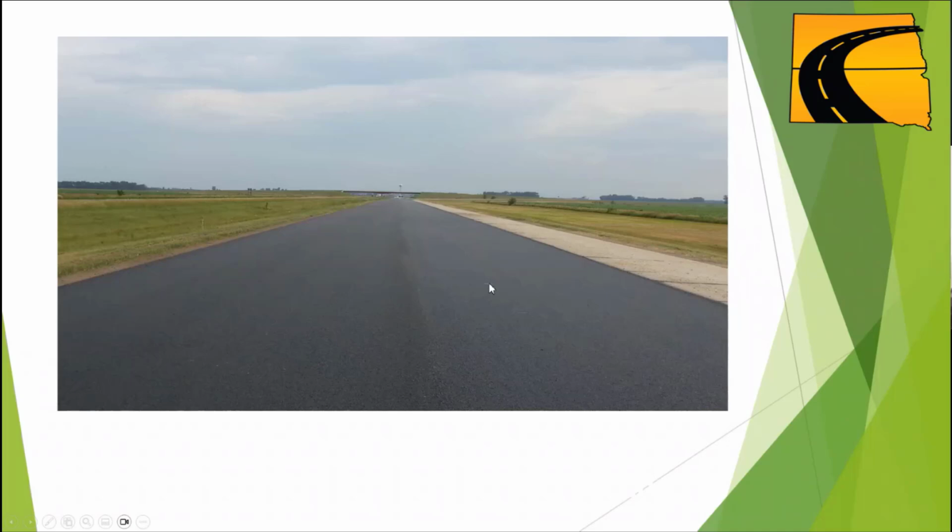This is a fat spot, where some of that oil migrates in the mix to the surface. And that's why you're feeding fiber into that operation: you want to keep that asphalt. You don't want it in the truck after it dumps its load. It costs a lot of money for that asphalt, and you want it in the mix and homogeneous in the mix.